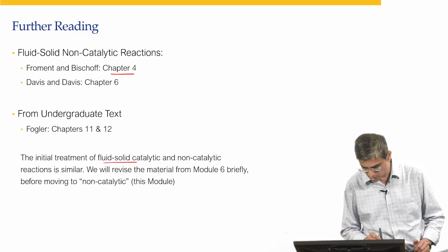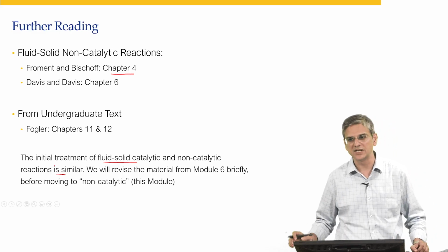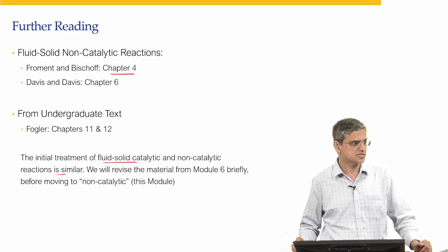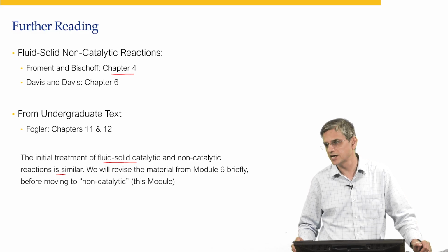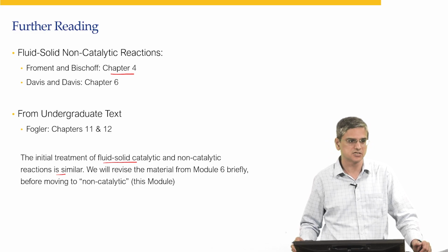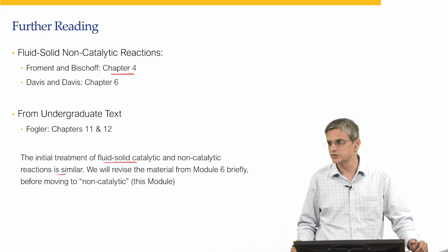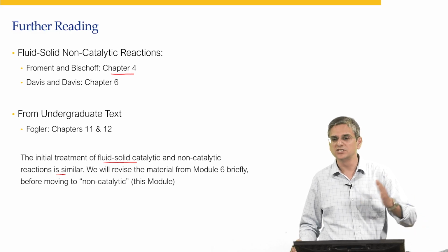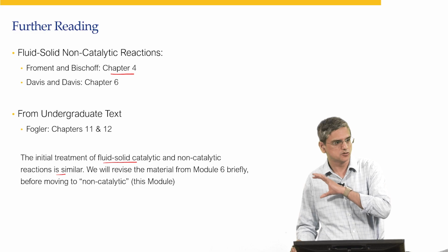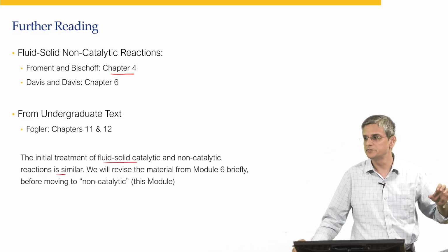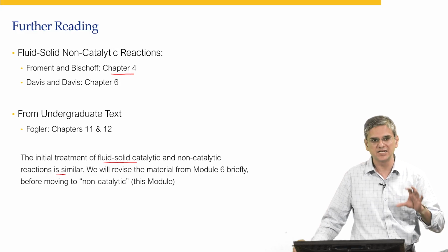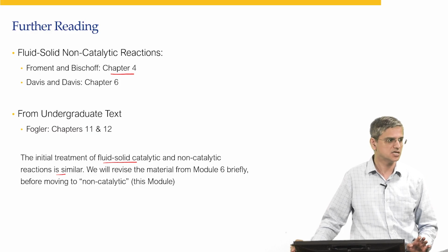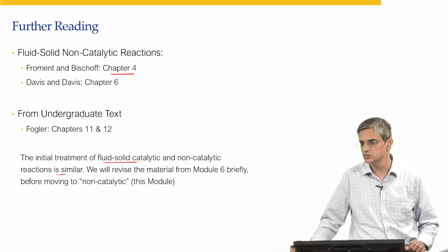So that talks about how the reaction takes place within the pellet itself or on the surface of the pellet. Thereafter, because of the reaction that is taking place in the pellet, whether it is a catalyst pellet that is undergoing decoking or any solid that is undergoing reaction, there is a change that happens in the solid. Now this is where this particular module 6 differs from the previous module. In the previous module, what did we have? The catalyst pellet itself did not undergo any change, whereas here the difference is that the catalyst pellet or the solid pellet is going to undergo some change.